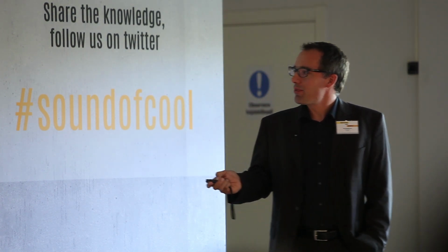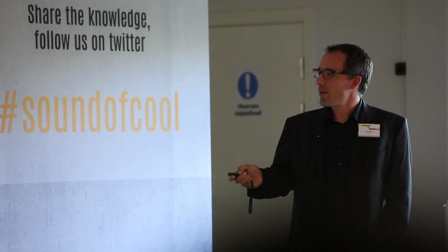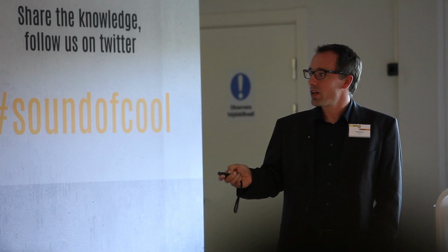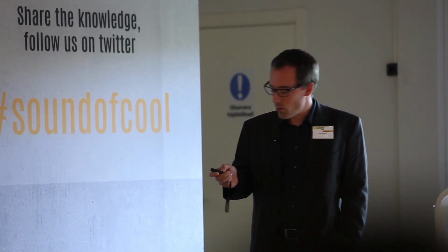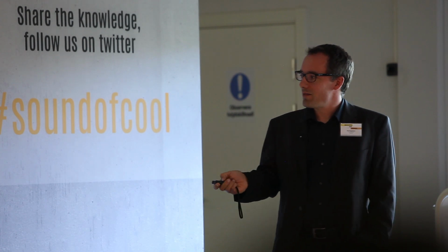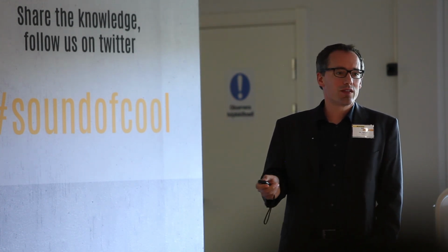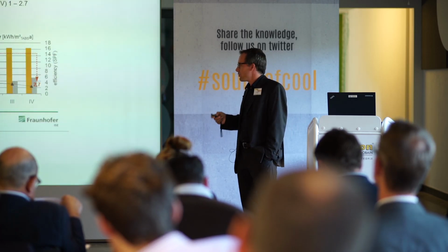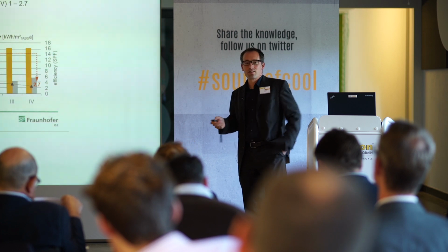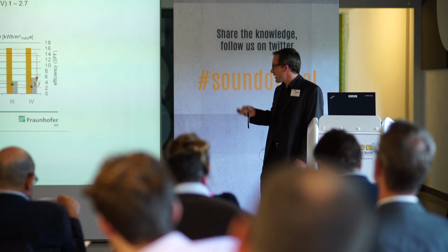So starting, of course, with a high seasonal performance factor from just looking at the source, we end up with a seasonal performance factor quite a bit lower. You can compare this to the COP, the coefficient of performance of heat pump systems, which the manufacturers typically give, because that only takes into account the heat pump itself and not all the auxiliary energy that's needed.